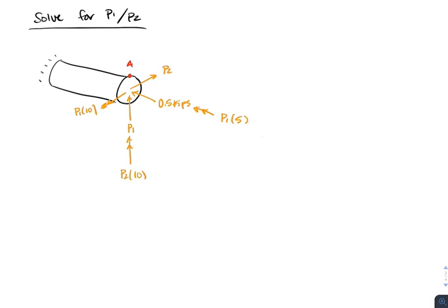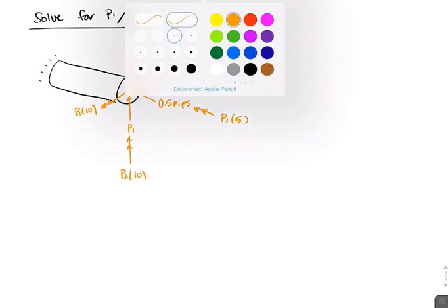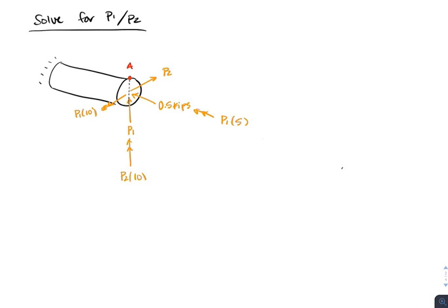If you had trouble seeing where all these come from, look back to your 204 notes, and you should be able to see that each of these forces, when moved, causes either a torque or a moment. From here, we can ask what kind of stresses our point A is experiencing. First, I'll draw the coordinate system, since I hadn't drawn that yet. In this direction is the positive z, up is the y, and along the beam is the x direction.